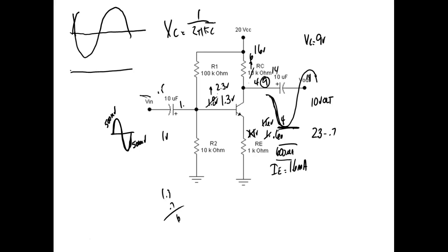What we've got though are these junctions right here, with a conductor on this side and a conductor on that side. So these act like extremely small capacitors. So these things have what they call a cutoff frequency, which means if the frequency gets up too high, the signal will bypass the base to emitter. It'll jump right through that parasitic capacitor. So what determines the low end frequency response is what size capacitors you use, this coupling capacitor. What determines the high end frequency response is the transistor.